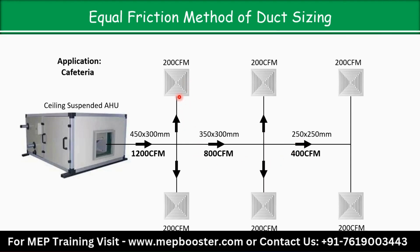Now for the branch duct, here the branch duct is going on, and each diffuser is of 200 CFM. So remember, if you are doing the sizing for a branch duct, the branch duct height should always be less than the height you have taken for the main duct. Suppose here the main duct height we have taken is 300 mm. So the branch duct height should be less than the height of the main duct. The reason is that to fix the branch duct to the main duct we have different flanges, and for that we need space, minimum 50 mm.